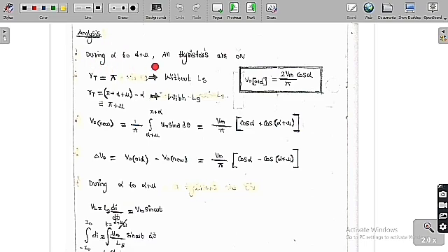During alpha to alpha plus mu, all the thyristors are conducting, because the source current cannot change instantaneously. Because of this reason, each and every device is going to conduct. So from alpha to alpha plus mu, all thyristors are conducting. So now, without Ls, what is the conduction angle of the thyristor?